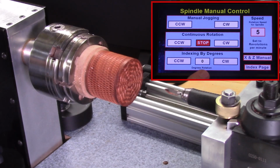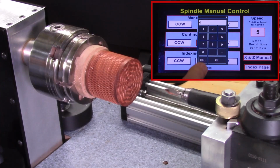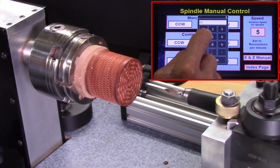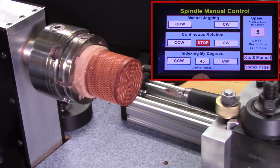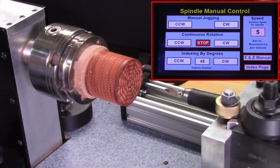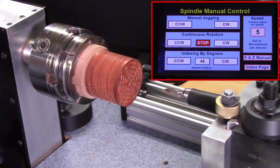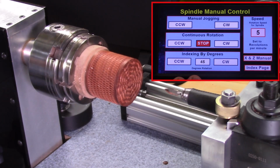You set the number of degrees you want it to rotate. For instance, if I want it to run, say 45 degrees, type 45 degrees in there, say clockwise, it'll turn an eighth of a turn and then stop. Have it run reverse, the same thing. So this is used when you want to have a program make some patterns on your piece, rotate it a certain number of degrees and repeat it.